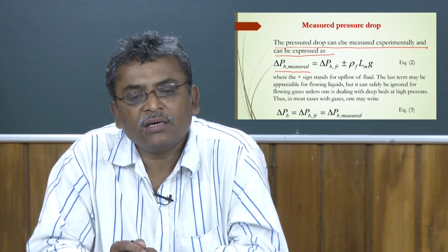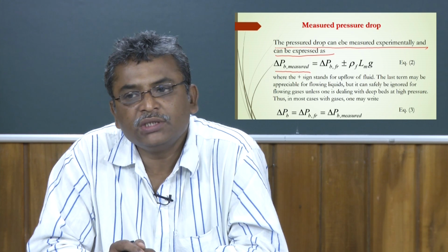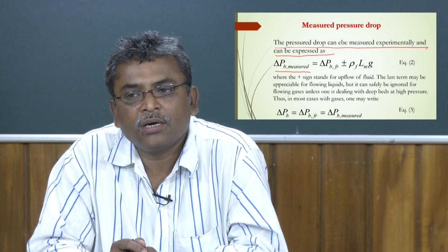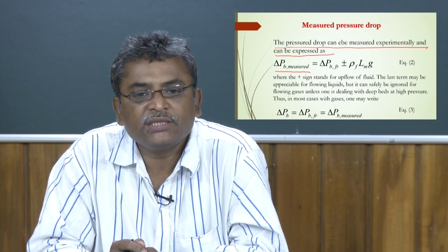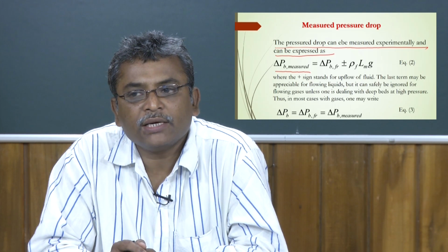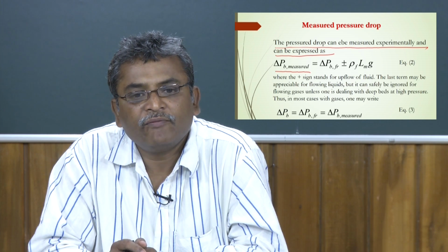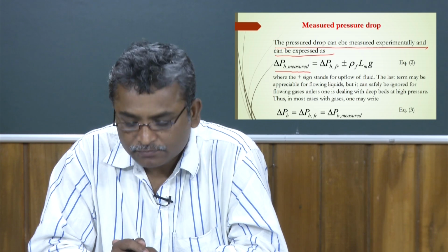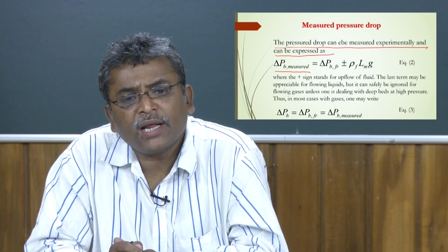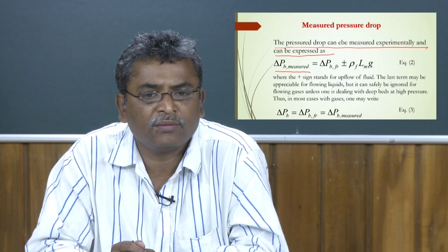Now, if you consider gas-solid fluidization, the hydrostatic pressure, because the density of the fluid as a gas is very small, is very negligible compared to the frictional part. So, here you can say that the frictional pressure drop is equal to the measured pressure drop.